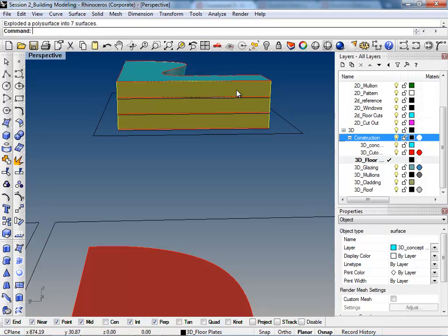And I would go into the perspective mode, the perspective viewport. And so those are surfaces, correct? Yeah. All right, so I would go up to solid, or up here, just click on solid on the menu up here. Sorry. Extrude surface straight. Yep. And type in -1.